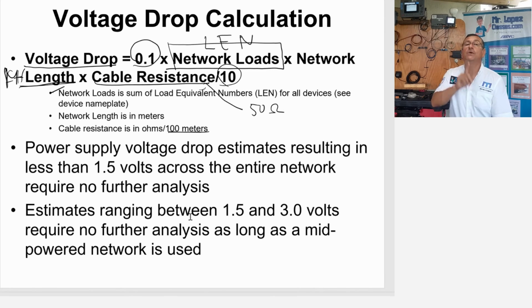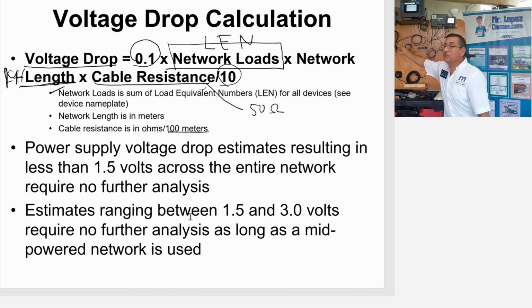Okay, be careful with the intensity. You can add more sources of power, but no more than 8 amps on the backbone. Be careful with that. This is critical. For that reason, the introduction of the fuses is very important.